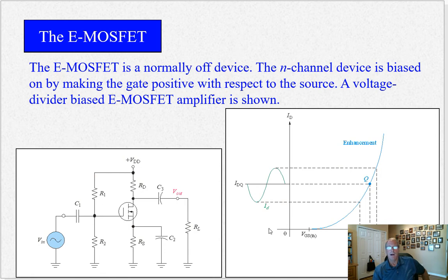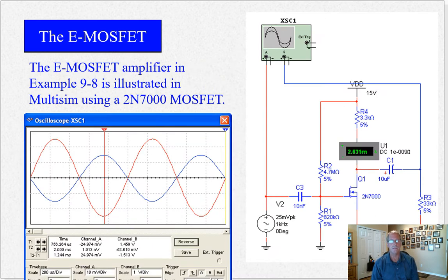The enhancement mode requires a bias. Okay, so you have to bias it in the positive, the VGS in the positive direction, high positive voltage. Which is okay, just adds another resistor here, and works the same way as the DMOSFET, except you now have a biased gate, the positive voltage. Both are used. The DMOSFET's a little simpler. And here is a little Multisim example showing the DMOSFET. Obviously, this probe here is at the front of this capacitor, because if it was over here, it would show that this curve would be offset by the bias, right, by this voltage divider. Shows a little gain here.